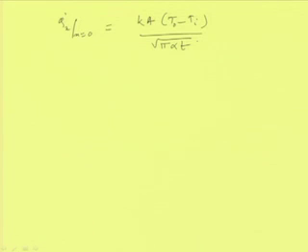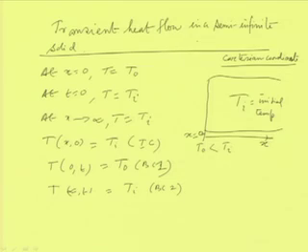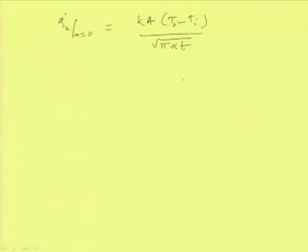Okay. So, as T naught minus T I is a negative quantity, the heat will be flowing from the wall to the surroundings. From the figure you can see that this will be the direction of heat transfer, from wall to the surface. So, q dot minus x is the direction of heat transfer. So, this is the temperature profile and heat flow rate that we can find out.